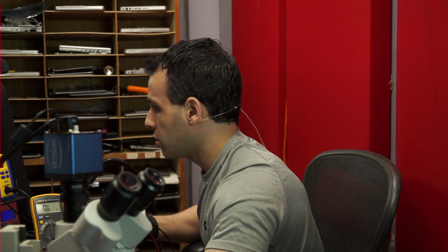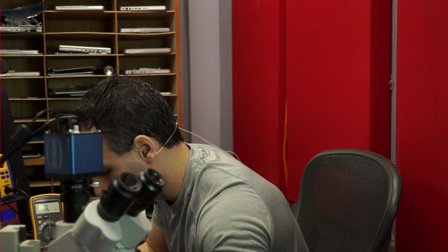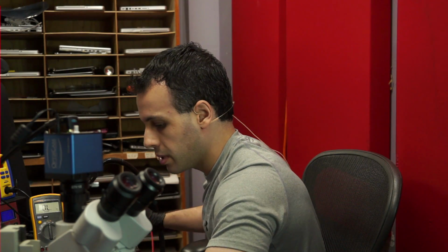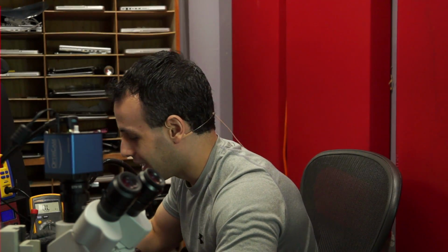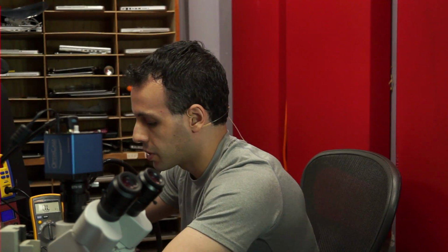So if we check the fuse, we're going to put the multimeter here in continuity mode, which is going to give us a nice 0 if we connect the two probes together, and we're going to check the backlight fuse before we go further. So when I check the backlight fuse, you'll see here that I get 0, which means that the fuse is good. Whew. That would have made me look pretty stupid if I were doing all this work when all I needed to do was replace a fuse.